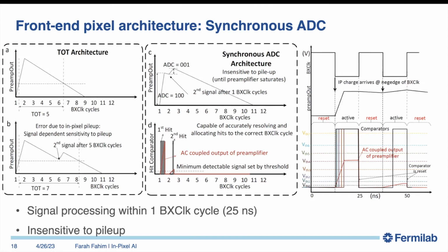That means at the end of every 25 nanosecond frame, if I want to do inference, I need to make sure I am comparing information from all the different pixels at the exact same time stamp, which means I need a buffer inside the pixel and some logic that realigns the frame correctly, and then I can do post-processing.